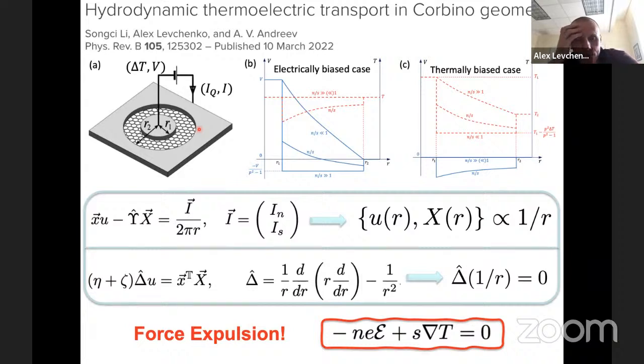So then you're puzzled a little bit for a second and say, well, okay, I already know what my distribution of potential is and the distribution of hydrodynamic velocities, so what does Navier-Stokes tell me? And then, to your amusement, you would discover that if you take the 1 over R solution into the projected radial component of the Navier-Stokes equation in cylindrical coordinates, you will discover immediately that the left-hand side that gives you viscous stresses, this operator in the radial coordinates, applied to a function which is 1 over R, gives you 0.